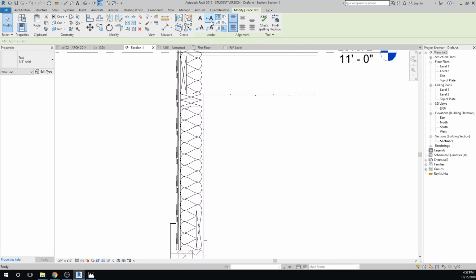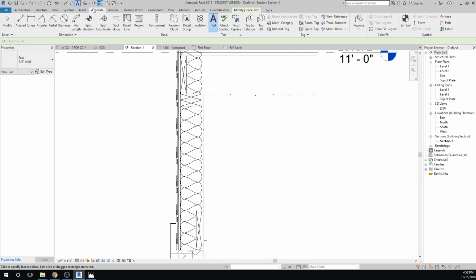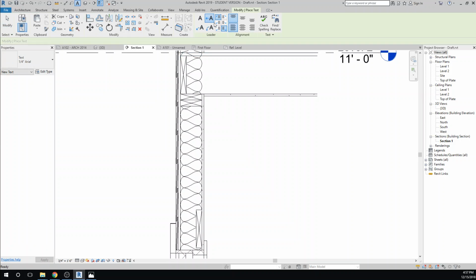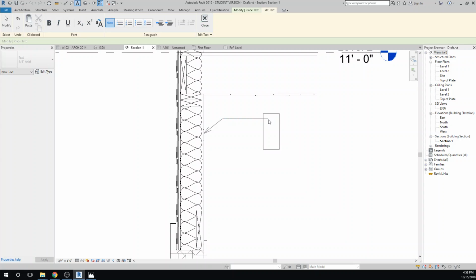One of them is to annotate, start labeling things. What I'll do is I'll just show you the basic technique of annotating. So we're going to grab the text tool under annotate. Once you select that tool, excuse me, let me just click out of this again. It just didn't do that quite the way we wanted to. I'm going to select the annotate tool, and when I'm in that mode, I'll get this idea of having a leader line, and I can touch the object and pull off and come out and then start typing.